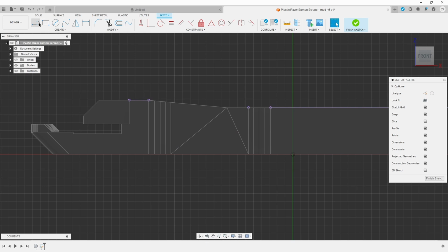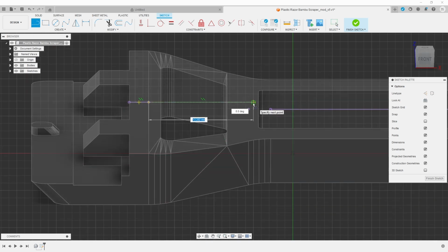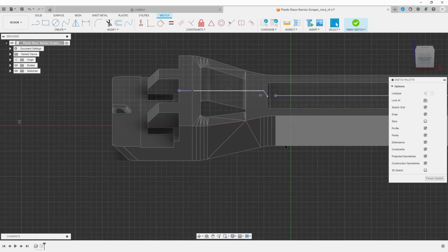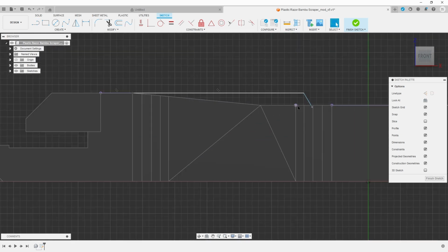Unless you're using adjustable layer height, there's not a way for it to do it very smoothly. So the simple solution for this, and this is really an aesthetic choice, is I'm flattening out that feature and then putting it in a 45-degree angle so that it will be a very clean step up and you won't have that stepped curve.